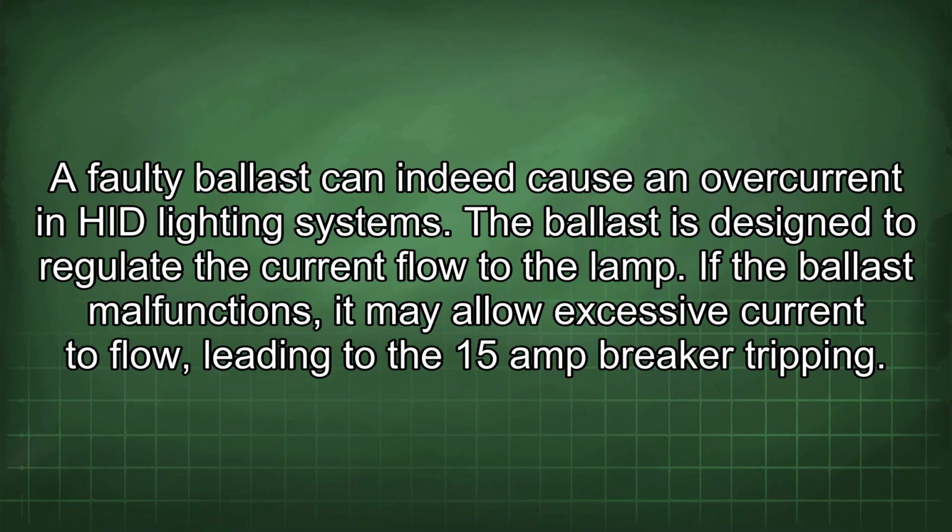Faulty ballast can indeed cause an overcurrent in HID lighting systems. The ballast is designed to regulate the current flow to the lamp. If the ballast malfunctions, it may allow excessive current to flow, leading to the 15-amp breaker tripping.